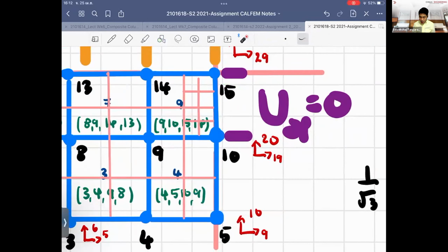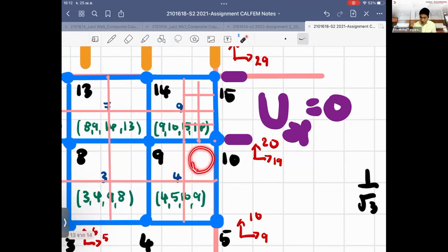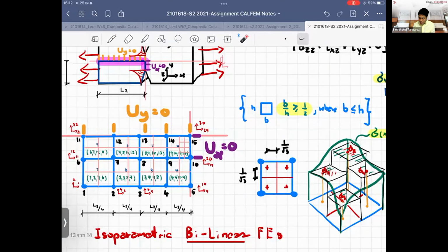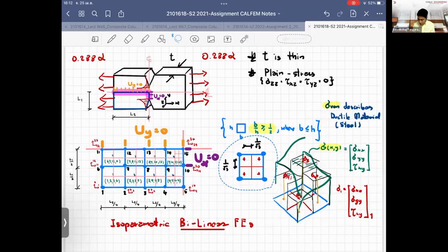So you might see that to make it compatible, when I discretize over these regions, it will make a node here. You see, it's clear, right? When there is a node here, and if we don't discretize the neighboring element, this element cannot be formed, because we have 5 nodes. If the 5 nodes come and match with the 4 nodes, we create a problem. The problem that we find for this 5 node, we call a hanging node, which we don't want to happen.